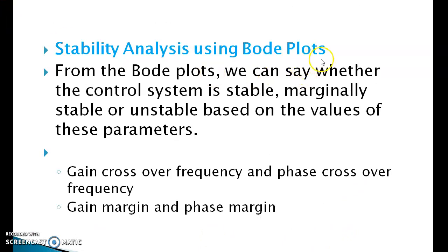Stability analysis using Bode plot. From the Bode plots we can say whether the control system is stable, marginally stable or unstable based on the values of these parameters: gain crossover frequency and phase crossover frequency, then gain margin and phase margin.